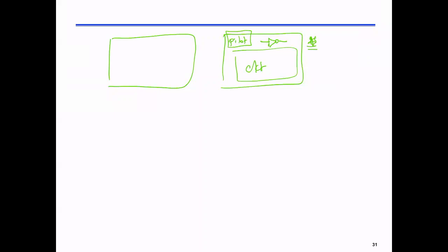So what they do is they put some circuit element that generates a clock, which has a wide range. Let us say the period T is a few nanoseconds or tens of nanoseconds, and they measure the oscillating frequency of the circuit. And if they find that, for example, this batch is fast, this batch is slow, then they start to divide them, the one that operates at 1 gigahertz, the one that operates at 2 gigahertz, and something of that sort. To build this, they really use inverters, just the very basic circuit. But let me ask you this question first.